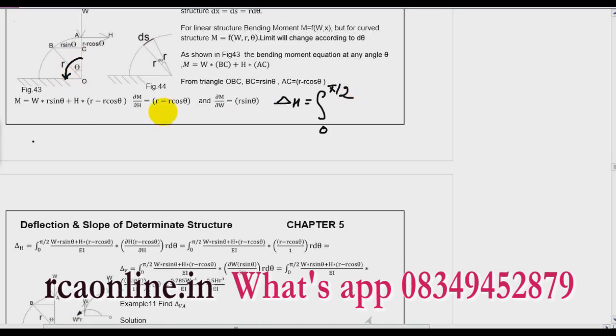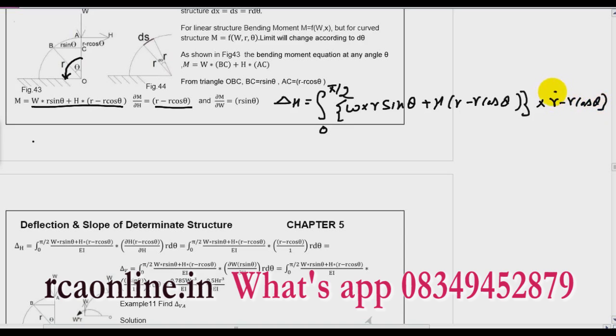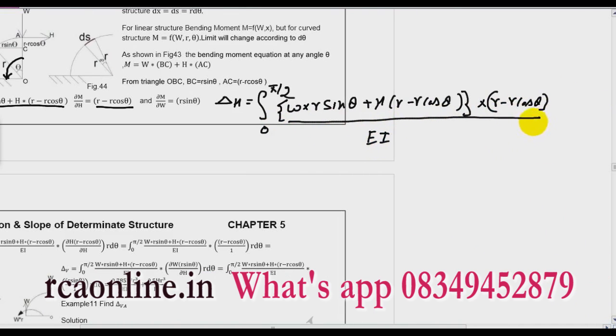Now what is my bending moment equation? This is my bending moment equation. And what is del M by del H? It will be R minus R cos theta. So W into R sin theta plus H into (R minus R cos theta), multiplied by (R minus R cos theta), divided by EI, and most important, in place of dx, I will put R d theta. If you solve this, what will you get?